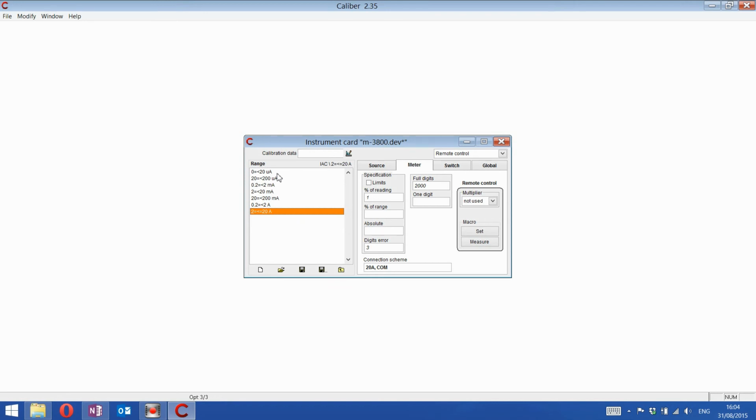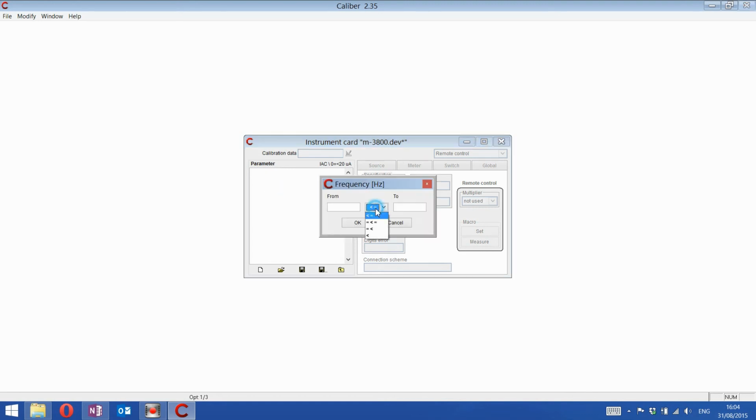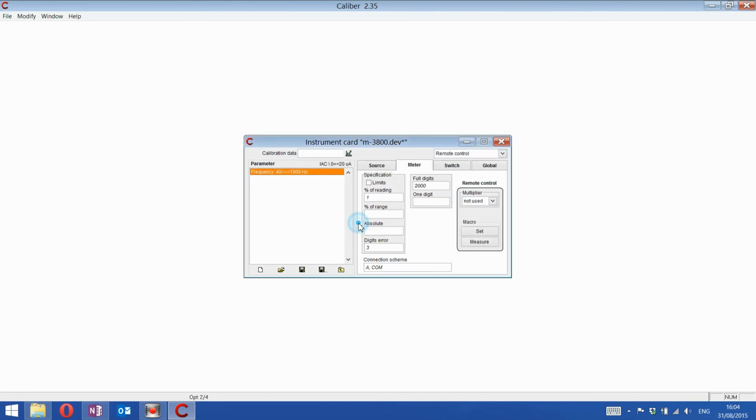In some functions, values like this are noted as parameters. Parameters have intervals similar to ranges, and every interval can have different instrument data. Think about electronic loads and the constant resistance function. You have a 10 ohms calibration point, but you can load it with 1 watt or 1 kilowatt, for which you could have a different connection scheme and specifications. In Calibre, you can use a load function with main value in ohms and parameter in watts or amps.